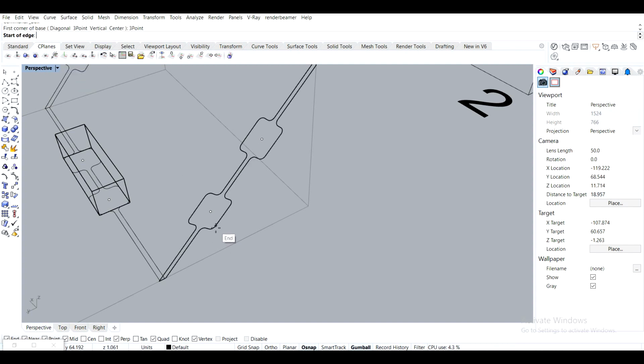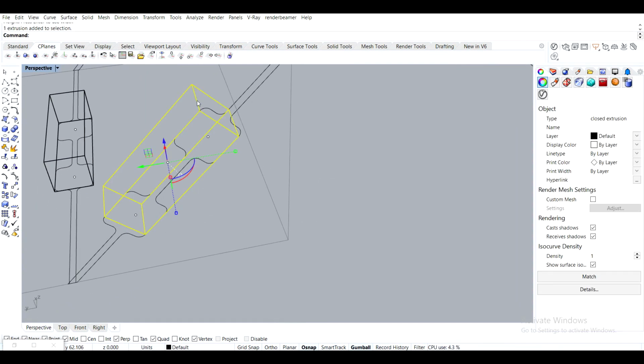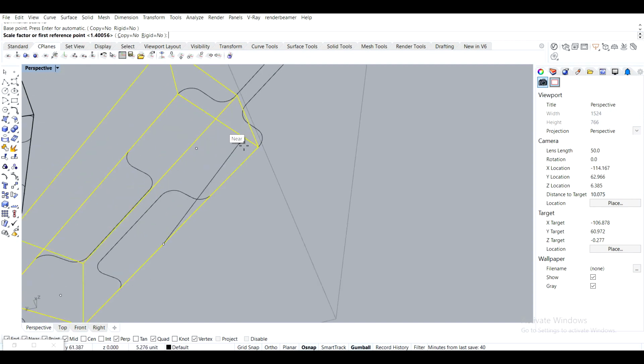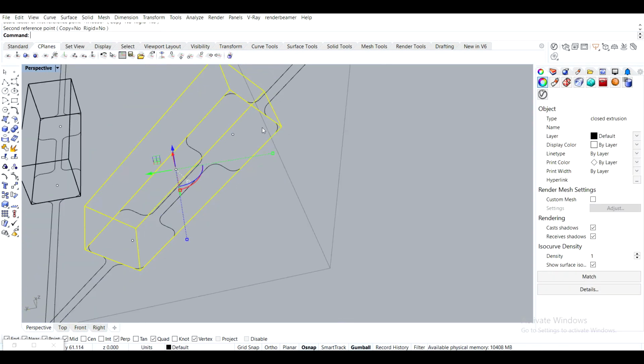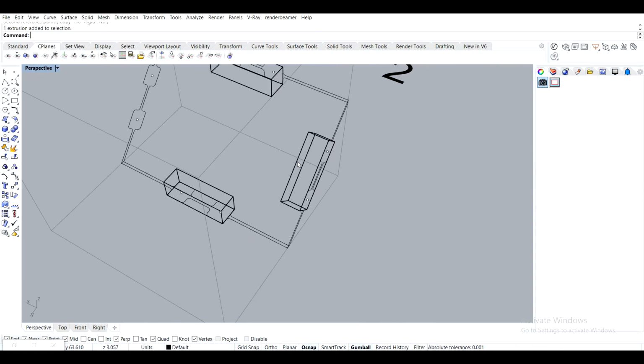So a 3-point box from this point to this point to this point, and then inwards by 1. Okay, fine, -1. So it does that, and then I can still do scale 1D from the midpoint to here up until here. Yeah, something like this. That seems good.